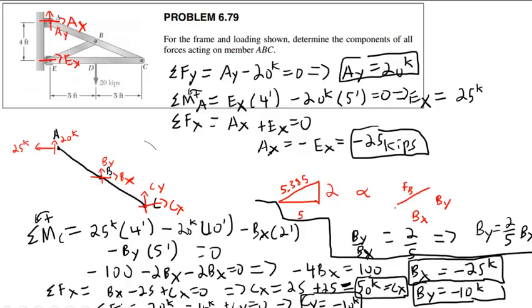All right, questions on that? Can you state that again? So we make the free body diagram, and you said forces that are not acting on the free body diagram will not be included in our moment. Yes, again, the only forces that will show up in your sum of forces calculations or your balance of moment calculations will be those that are present on the free body diagram of that member. Okay? We are not balancing forces on the entire structure. We're only balancing forces on that member at this point of analysis. Okay. All right, other questions?